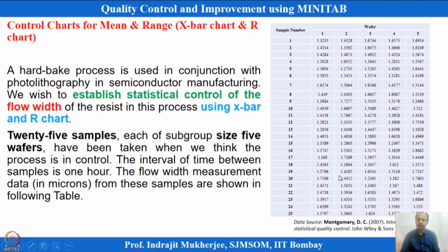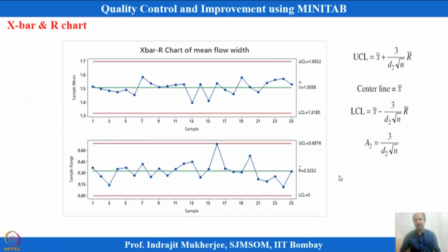When you calculate the control limit lines, there is a formulation for calculating the natural limits. I told you that the variability of a process is defined as plus 3 sigma on one side and minus 3 sigma on the other side. Based on the concept that the variability will be within normal distribution assumptions, 99.73 percent of the observations should lie within plus or minus 3 standard deviations.